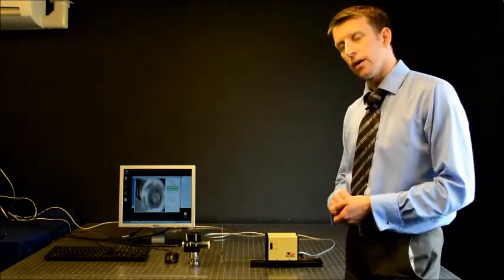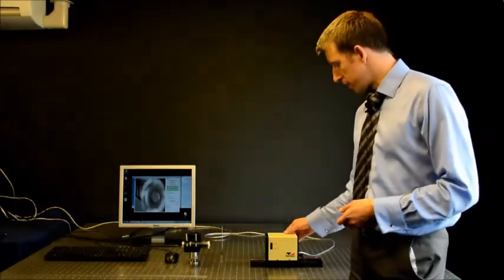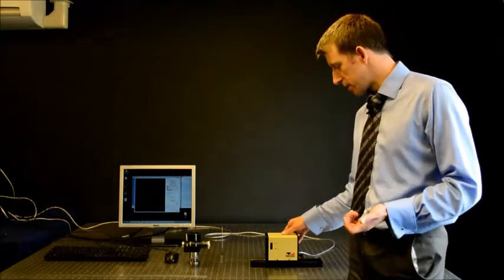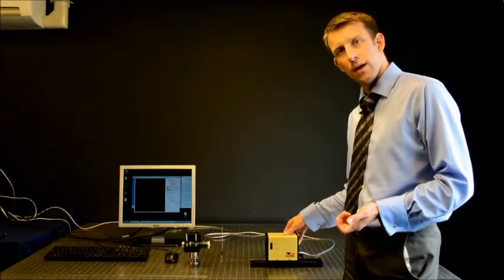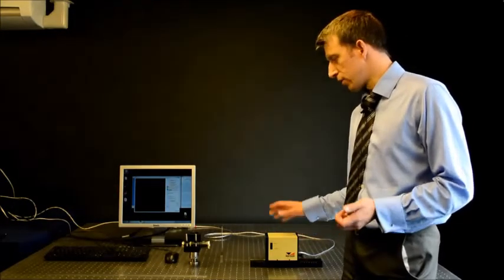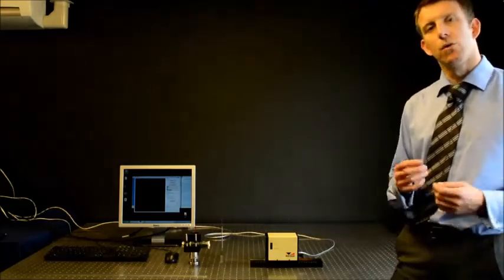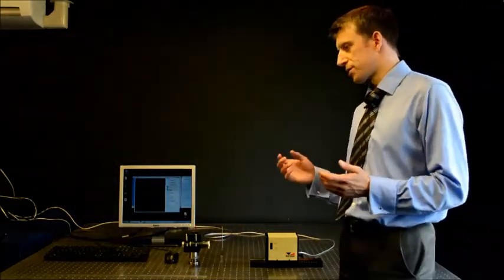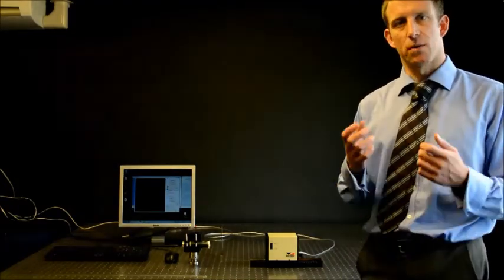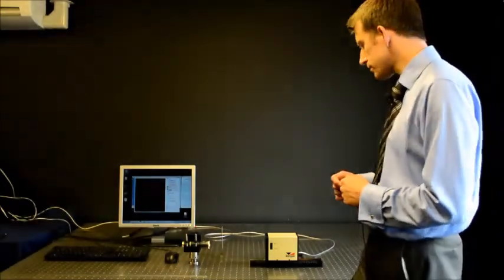And having illuminated the source, we insert filters in index positions, ND3, ND4, ND5, and then ND6. Then we have a closed position. This closed position is used for the purposes of measuring the dark pixels of the camera. It is a one-off procedure effectively.